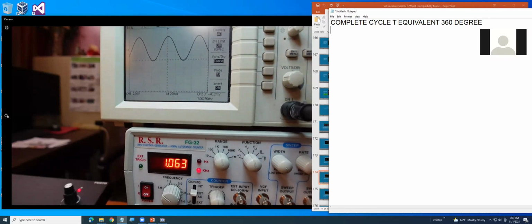Okay, now you have to tell me, for one complete cycle, how many divisions for the time? On the screen there, try to have only one sine wave. That's what I want to see, one cycle of this signal. How many divisions? Exactly. Right now, you have four divisions.